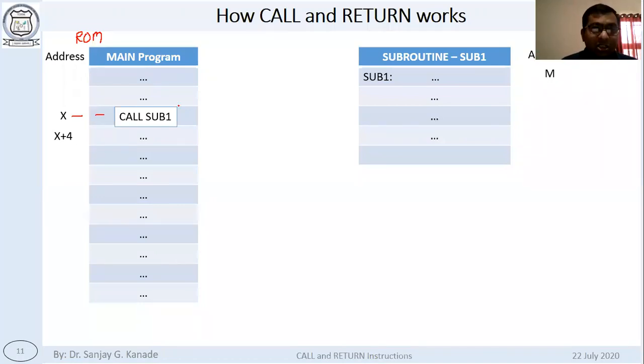We have written instructions in the main program, and let's say the call instruction is written at address X. Now, if you can recall, the call instruction is a 4-byte instruction, right? That's why the next instruction after call is at address X plus 4. Clear?